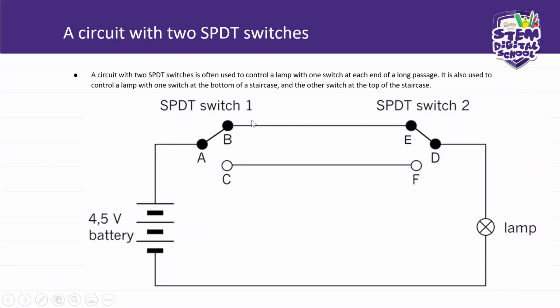That's why they made an example even of the staircase. If you go up the staircase and it's dark, you can switch the light on at the bottom of the staircase. And when you reach the top, maybe the first floor, you want to turn off the light, you can use the switch on the top, on the first floor, to turn off the light. Okay, so you have two switches for one output component. So you have a single pole double throw switch. Okay.